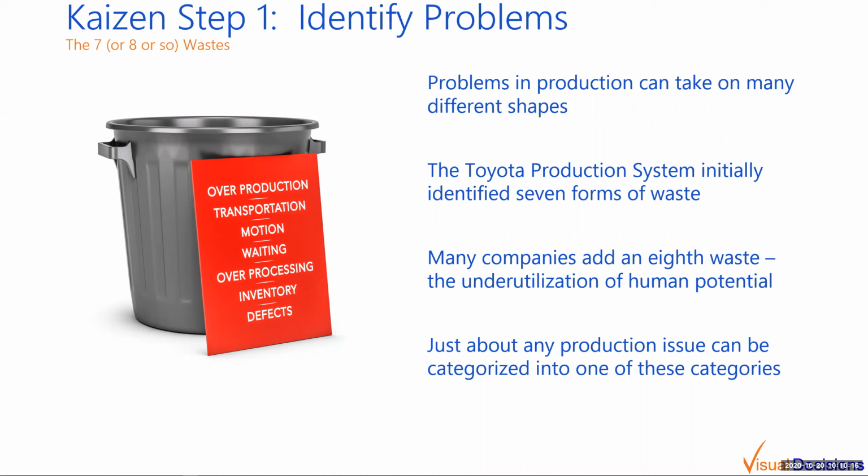The next step, which bleeds over into step 2, is that not only do you want to collect information about, for instance, defects, but you also want to be able to collect information about the reasons for those defects. It's not enough to know that my first pass yield went from 97% to 93%. That's not actionable. It means I need to pay attention to it, and it's good to know. But until I know why it went from 97 to 93, there's nothing I can really do about it.